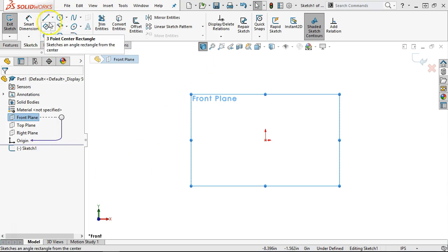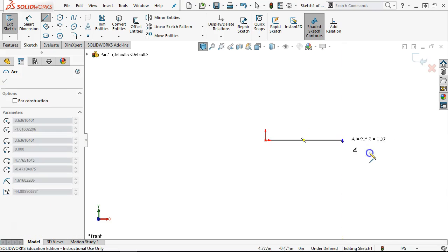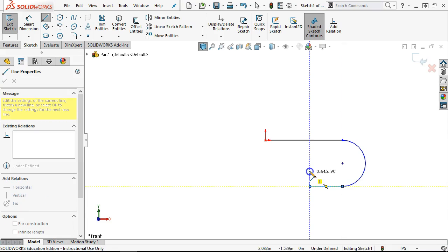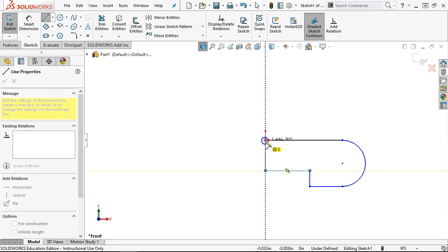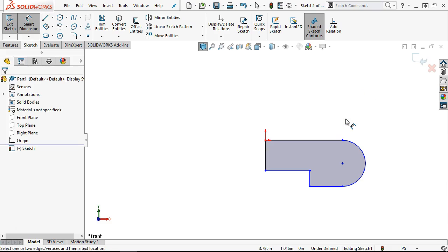I don't really need a rectangular shape. It comes down and goes over, so the sketch will be to the side. Go ahead and make a continuous arc, so the tangent, go back to the start point. You should be getting pretty comfortable with that by now. It's an effective method of creating our geometry. And so we close that off. We'll go into the dimension.